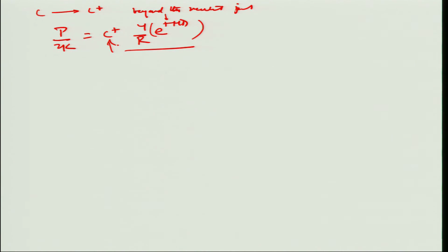So in this particular case, at the final separation or at the end of the rolling process, if the thickness Tf has been achieved, the roll pressure Pf by 2K should be equal to 1 minus sigma xf by 2K, where this is the final principal stress on the sheet at the exit point.